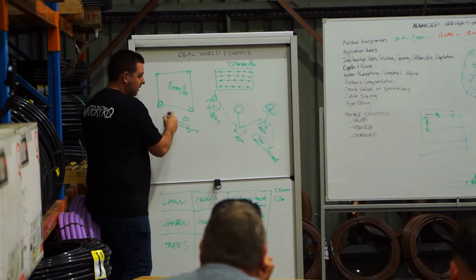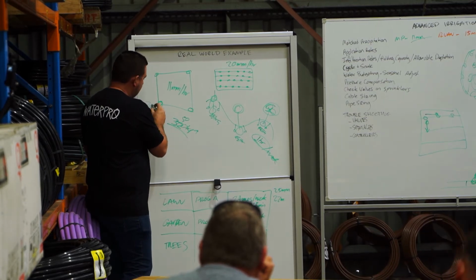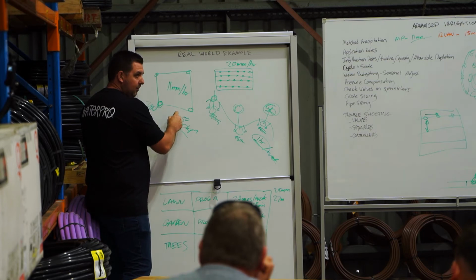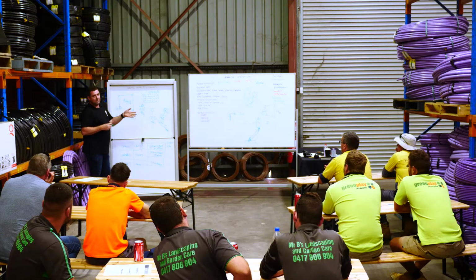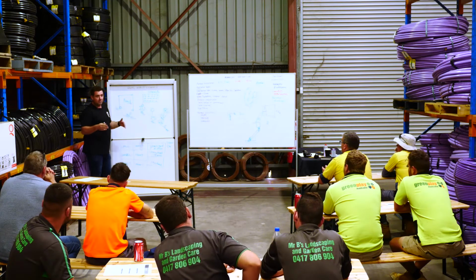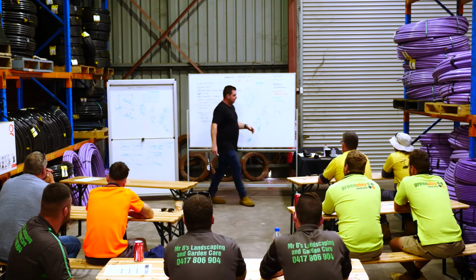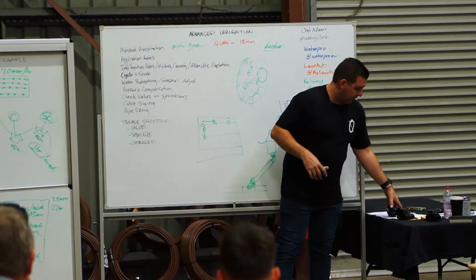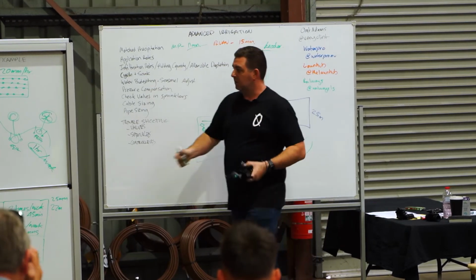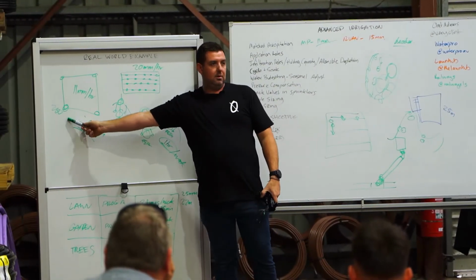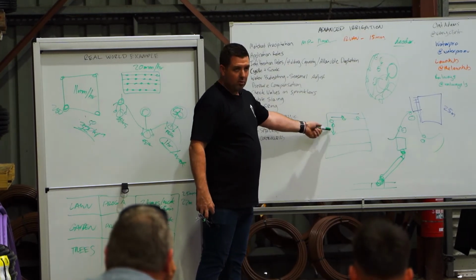And then I was saying, you know, if it loses 50 here, 50 there, 50 there, if you get to the point where this actually only was 320 and you needed 280 here, if it goes through a non-return valve it will generally shave 50 kPa off. So even your 40 mil ones commercially, you'll lose about 50 kPa. A solenoid valve might take 20 kPa of pressure. Pressure and flow are different, and we've talked about this in basics of irrigation. If you lose too much pressure through all of the infrastructure, they won't pop up. And if you lose too much pressure to a point where there's not 100 kPa, they won't drip.